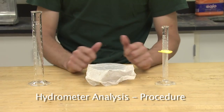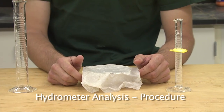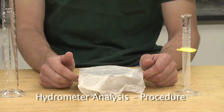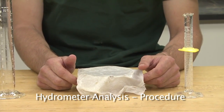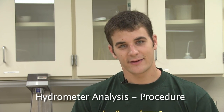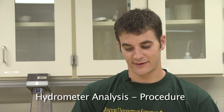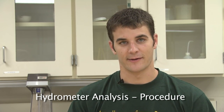The sodium hexametaphosphate is similar to laundry detergent. It works to break down the cohesion between the particles so that the individual particles will not stick together. Note, this is a deviation from the ASTM standard. ASTM suggests that you let this set for up to 24 hours. We will only let it sit for 15 minutes in the interest of time.